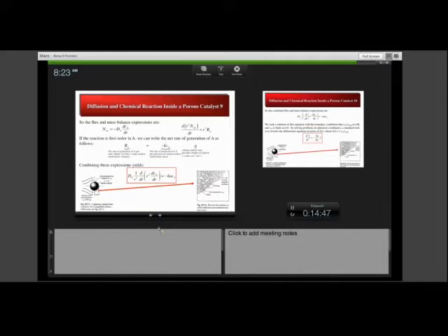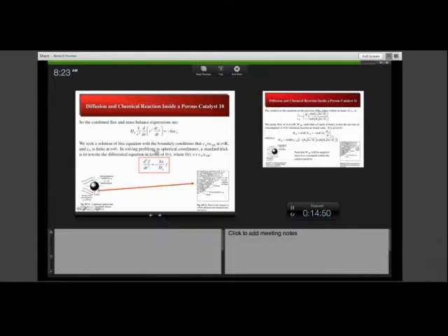So again, we see in these problems that involve surfaces that surface per unit volume enters the problem naturally. And we can now combine this detailed expression for the rate with our mass balance and our constitutive equation to get the differential equation for the concentration profile.